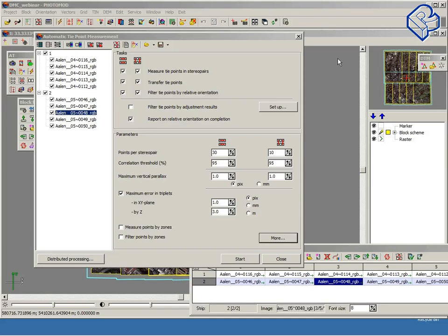And for ground control points like the ones we had in this project, we do not need stereo because the correlator works just fine. But if you have some ground control points on specific terrain features like buildings and fences, and the correlator doesn't work, and you are not sure about manual measurements, you will need stereo. But for this data it is definitely not needed.